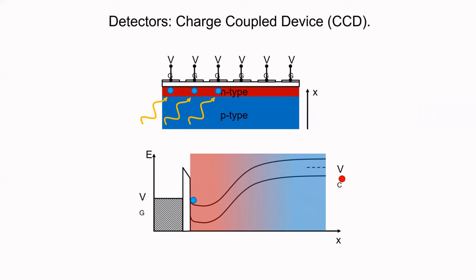But now you've got an electron sitting in the N-type region. But also, you've applied a gate voltage with that series of gates. By applying that gate voltage, we've dropped the potential of the N regions. We're actually reverse biasing our diode here, but it's only reverse biased laterally. In the top direction, it's only been reverse biased under those individual gates. So the electron is then held under those gates, so it can't go anywhere.